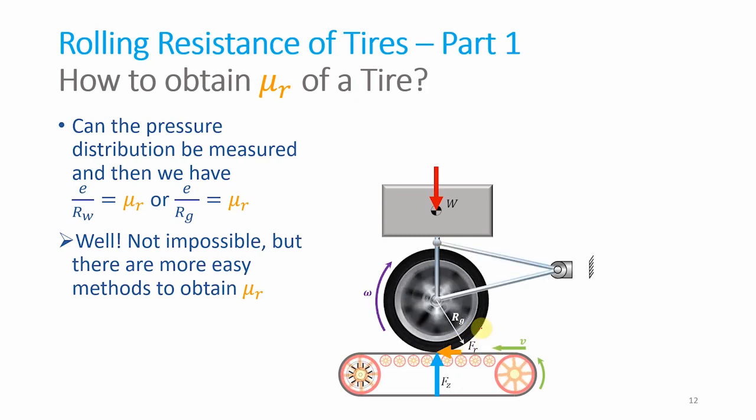Now let's support this tire and the weight by a structure which is attached to a rigid structure by a force transducer measuring device. What is the reason for having this force transducer device? Because this Fr which is appearing here can be measured here, because this is the only place where this Fr can be reacted. So this Fr is measured using the force transducer here.